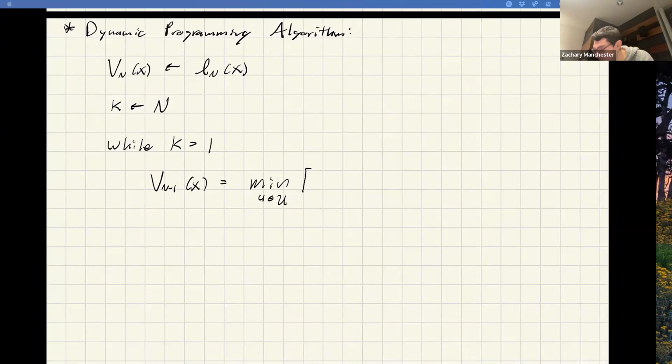We're going to do this, but importantly, this is a one-step min. It's a min over a particular u at a particular time step. And we're going to have the one-step cost in there, right? So for LQR, that's a single x transpose Qx plus u transpose Ru, single time step. And we're going to have the cost to go for the next time step with the dynamics plugged in, so that it's mapping the current state and control forward to the next state, plugging that in.